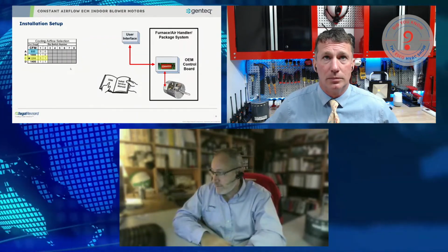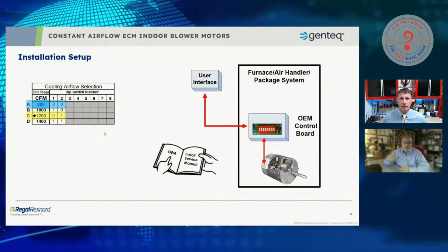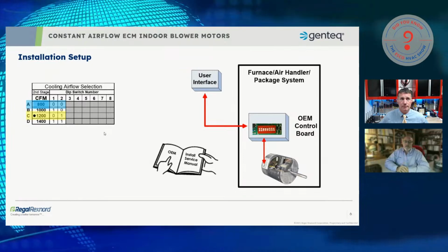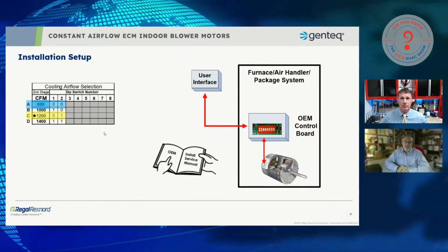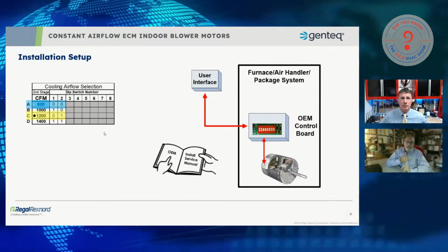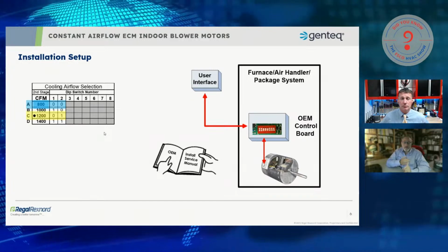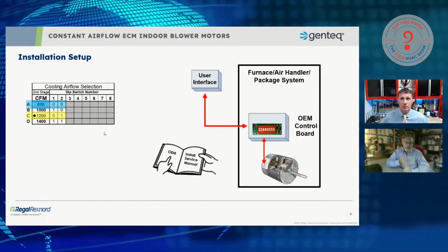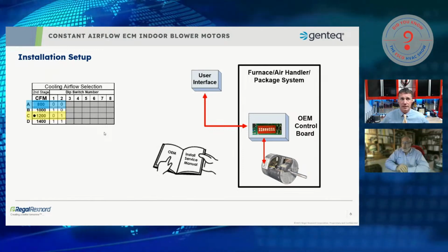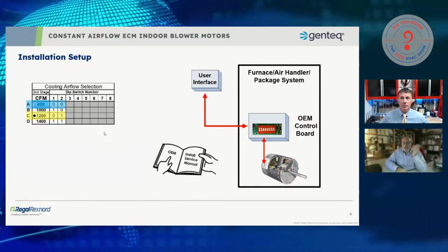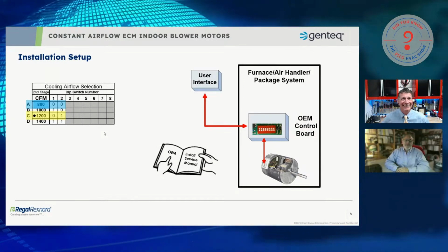That dip switch, and if we look very carefully, I'm going to show you, it would be one switch. That's all I have to move, one switch, and I have perfect airflow. And it's just that simple. So I could have not only customers complaining that, gee, the system's really loud. If I'm set at 3-ton, maybe I'm not getting very good dehumidification. And boy, I lost the motor at 7 years. That doesn't seem to make sense. Exactly. All because of one dip switch.